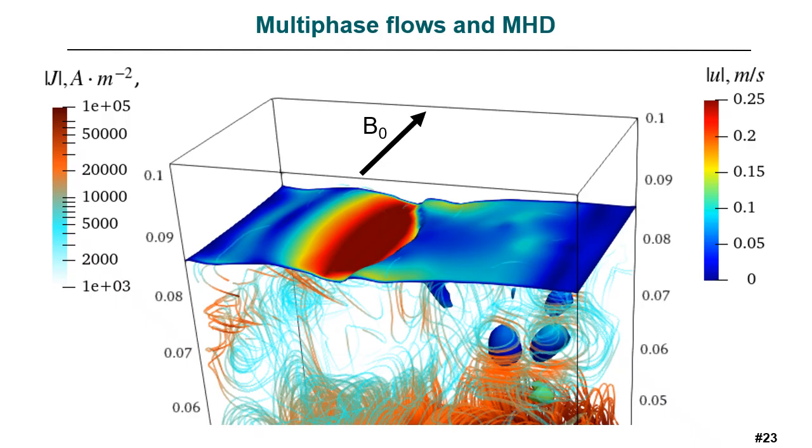The distribution of the induced electric current must also be carefully treated at the interface of the liquid melt and a second non-conductive phase, for example, slag bands, gas bubbles, or entrapped slag droplets.